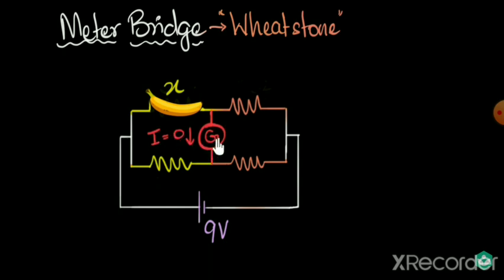Now you might ask, hey, here also the resistance of the galvanometer, won't it screw up our calculation just like before? No. Before, the resistances mattered because we were calculating values of voltage and current. Those values will change when we introduce the galvanometer or ammeter or voltmeter. But over here, notice, in this balancing condition, there is no current flowing through the galvanometer, right? So the galvanometer is not even a part of our circuit, and so its resistance won't matter at all.